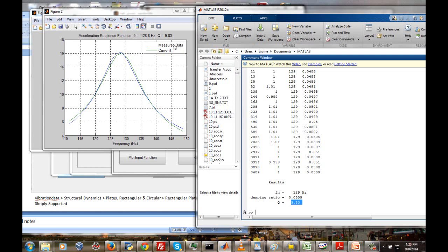So even though that peak is at 16, that's 16 G out divided by G in. Even though that's the peak at resonance, the Q value is still equal to 10, and we find that out by using the extension of the half-power bandwidth method via the curve fit.